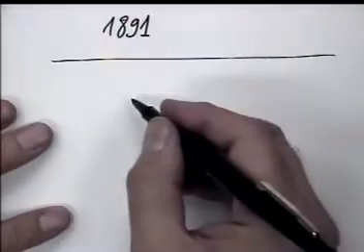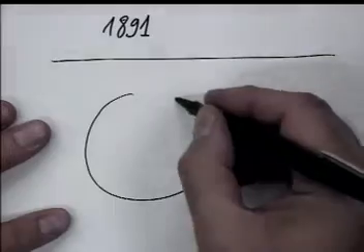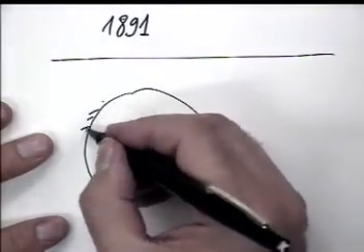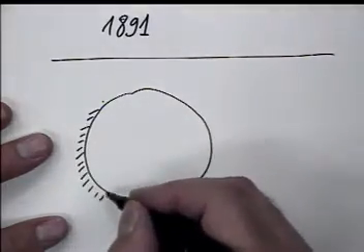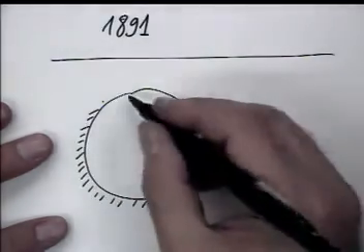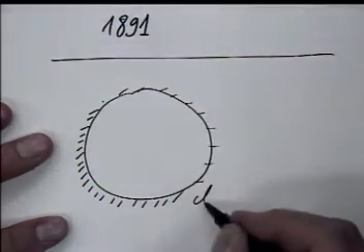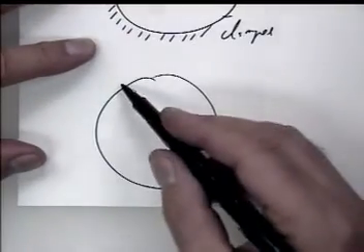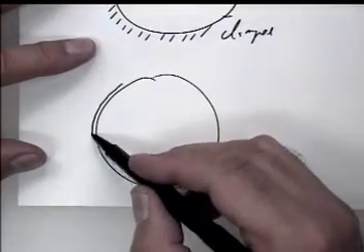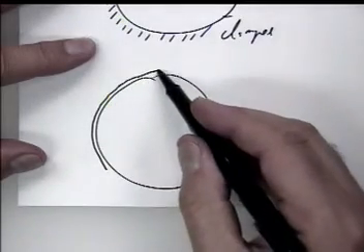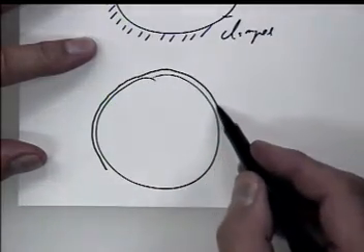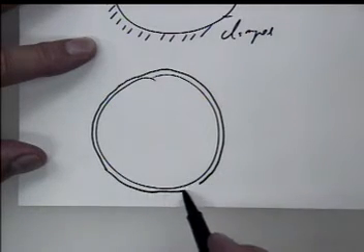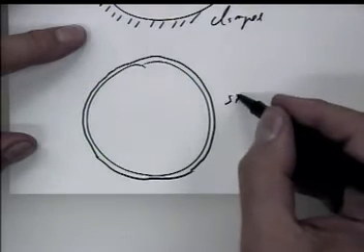Now, what happens if here it is simply supported? So first of all, clamped, we are denoting like this. That is clamped. Now, simply supported, we denote by another line, a concentric line here. This is actually a Russian notation. This is a concentric line, very close by. So that is simply supported.